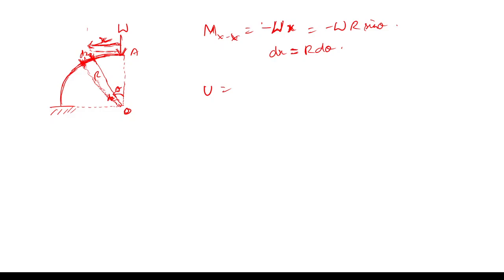Sir, I want to ask, what is the fault in taking dx equal to r cos theta d theta? Actually, you can't take it like that, because here x is the length of this string. If I take dx, it is something like differentiating r sine theta, differentiating this distance value. That is not required for this problem. I need to find the length of this small elemental strip or elemental ring, so it should be the radius multiplied by this small d theta. Then I can convert the integration in terms of theta.